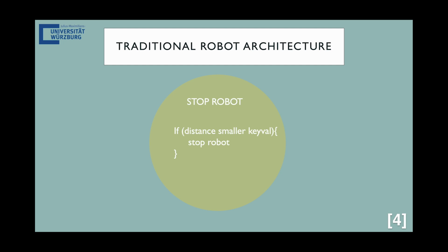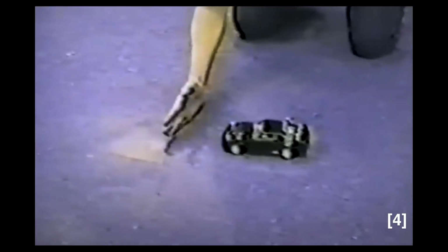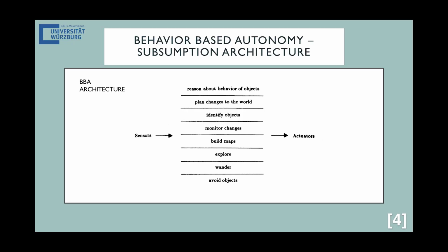If we now let these little programs run in parallel and implement this to our robot, we can basically call this our first behavior-based architecture. If we look at how Rodney Brooks implements his approach, we see that he also divides the tasks vertically. Through this vertical division of tasks, Brooks manages to break down the otherwise very complex merging of the various senses and the modeling and planning into many small, simple processes running in parallel.